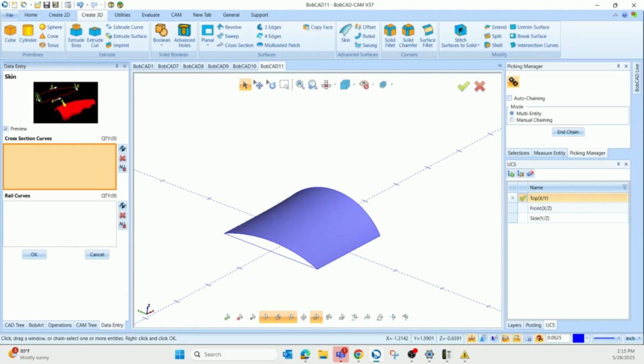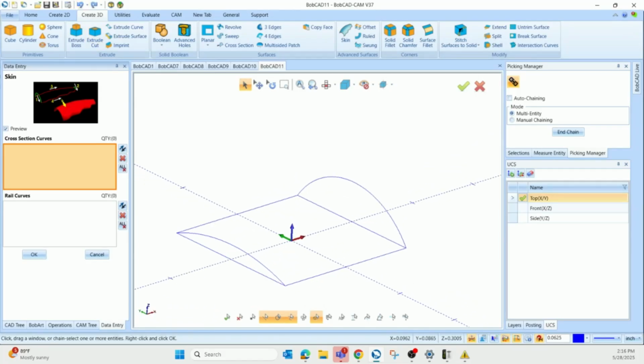It's just a little different workflow. Sometimes when you go into surfacing wireframe like this, you'll get different results based on your surfacing function. So if you get a problem with your surface in 4 edges, then you can try to create the surface in the skin surface function and maybe get a different result. In this example, I selected the lines first and then the arcs. Sometimes the surface comes out, how do I describe this? The surfaces come out as multiple surfaces.